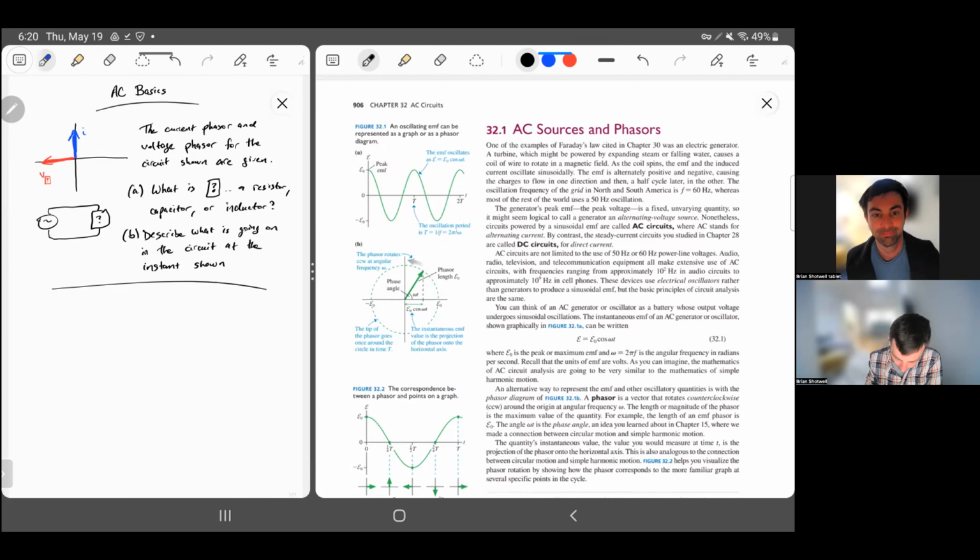And that is in terms of a phasor diagram. So that's what this thing is right here. These 2 things are representing the same information. So what a phasor, it sounds really complicated. All it means is an arrow that's rotating in space. So this arrow is rotating counterclockwise. So notice there's this direction symbolizing that this thing is rotating in time this way.